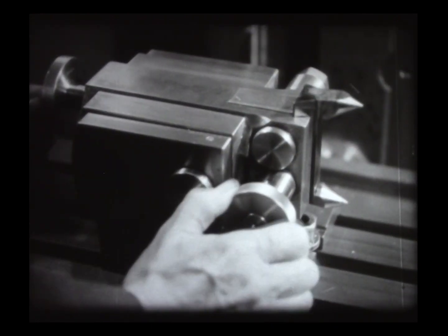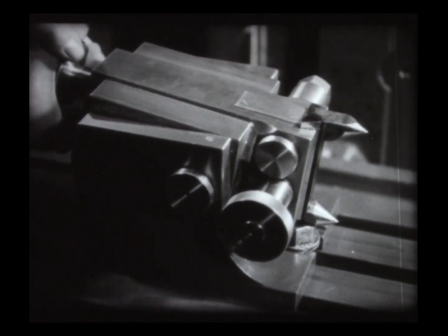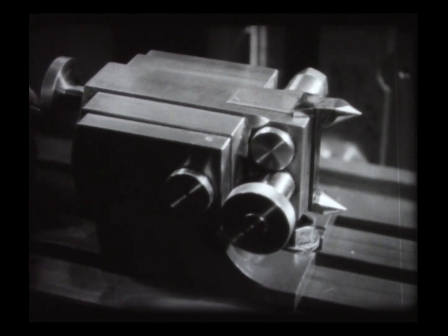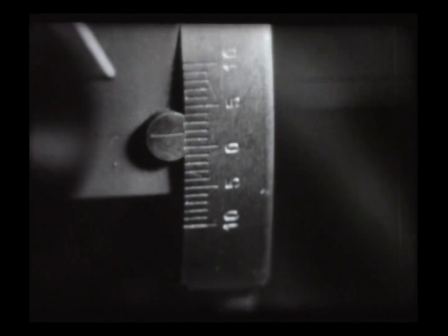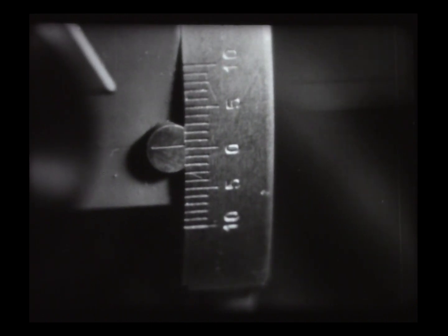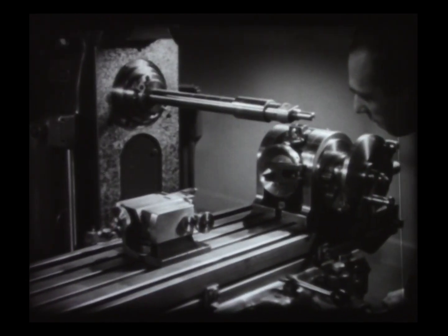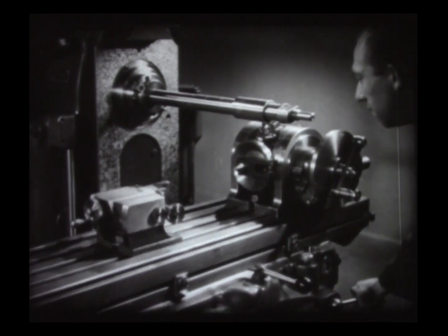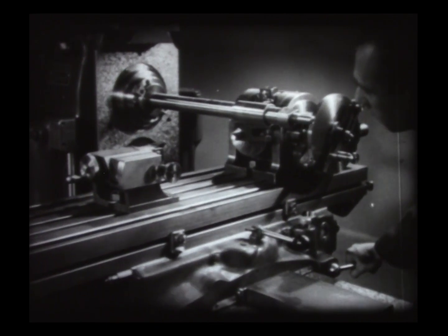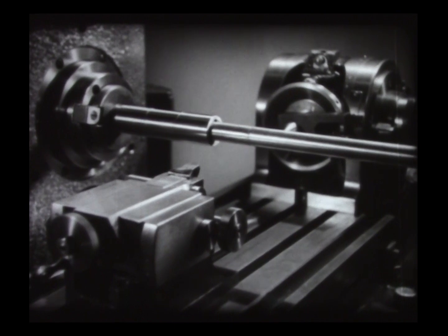The tailstock can be adjusted at various heights and angles. For a straight cut, as in milling a spur gear, the tailstock is set horizontal. This can be done accurately by means of a calibrated scale on the rear of the tailstock. To ensure a rigid cutter setup, the table is moved as close as possible to the head of the machine. The cutter is lined up with the approximate center of the headstock.